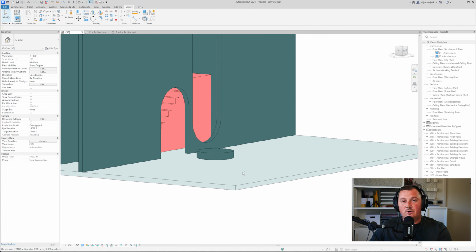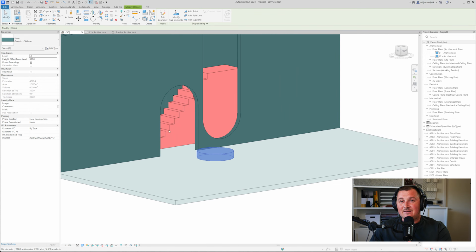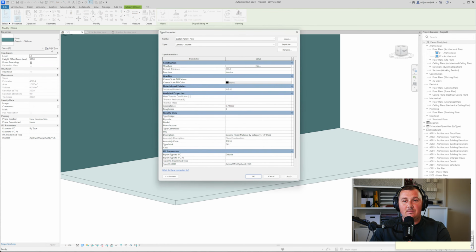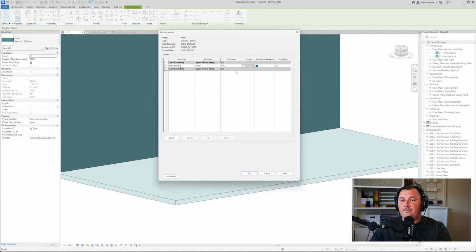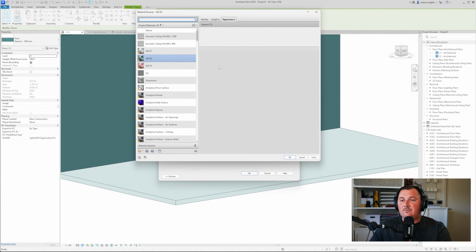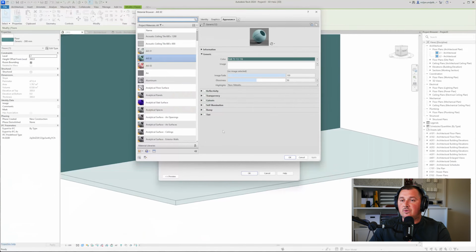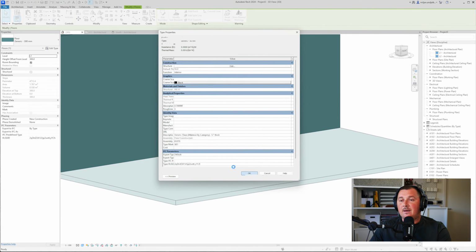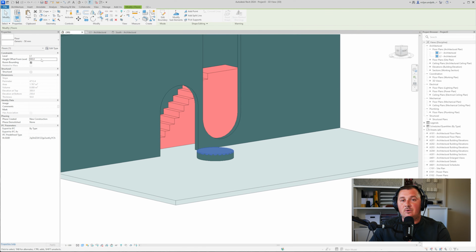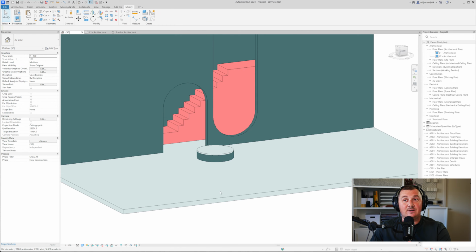As you saw, I forgot to change the thickness here as well. And let me just select this one. I'm going to go here to copy and then paste, and I'm going to align this to the same place, and then I'm going to go to duplicate and make one of 50 millimeters. And for this one, I'm going to use the first material. And what's also important, I'm going to make the height offset 350. So you see that we are done.